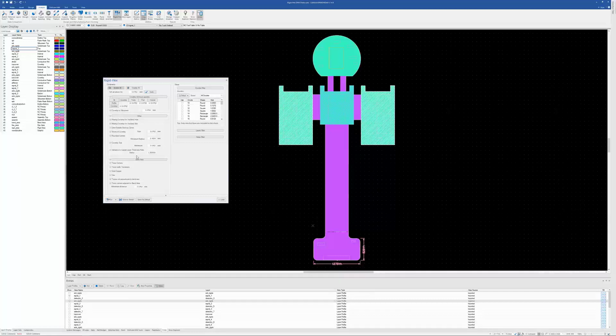All right, so these are some of the checks: cover lay spacing, cover lay to track, cover lay to pad, cover lay to copper, cover lay to cover lay. All of these can be set up and run, and we'll run these in just a second, but I just wanted to show them in the constraints panes here.